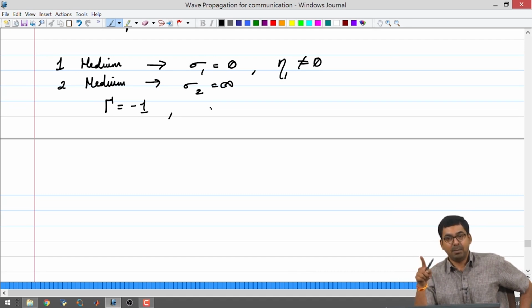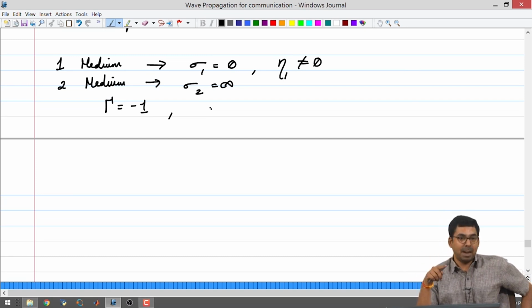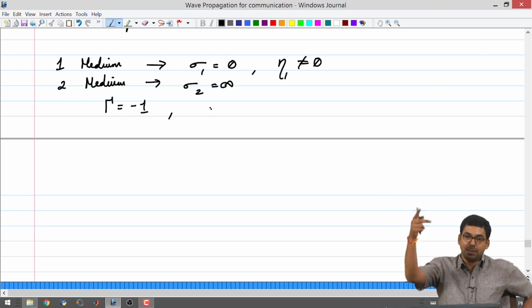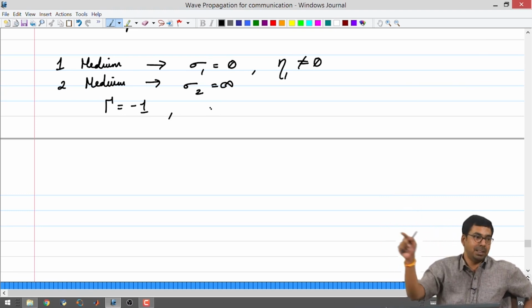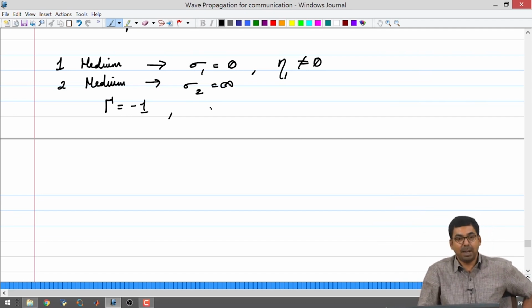When we ran a simulation with our codes, we had written Maxwell's equations in one dimension. Suppose we make one side a perfect electric conductor, which means you make the electric field equal to 0. Whatever the voltage, you will not get an electric field over there. If you do that, you will get a reflected wave which is flipped. We saw that an impulse will travel, get flipped in direction and then come back. So, gamma is equal to minus 1.